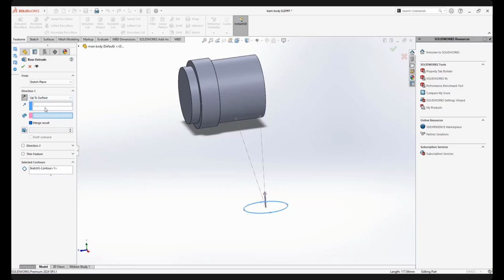Here, this area, you never focus on this before. Can you see the blue color up to surface? Normally when you use blind, you give this blue color here, this setting at the bottom, which is about the direction of extrusion. You can select any line, just now we created the 15 degree line, to be the direction of your extrusion. But now I'm using up to surface.